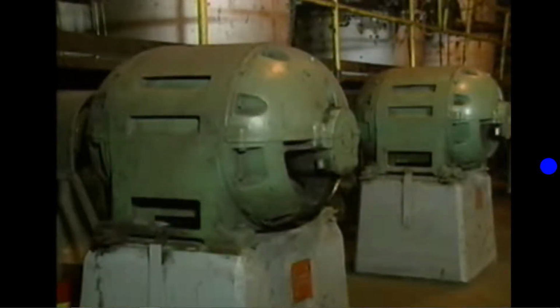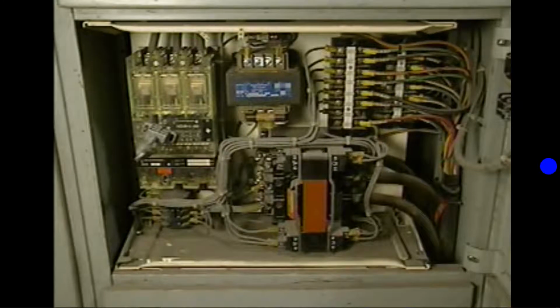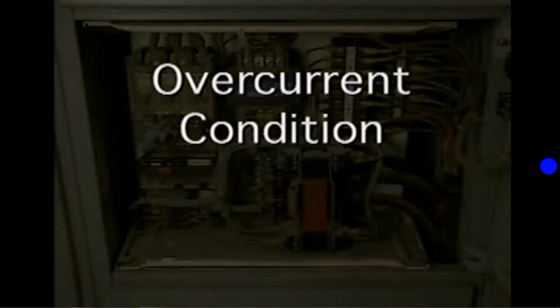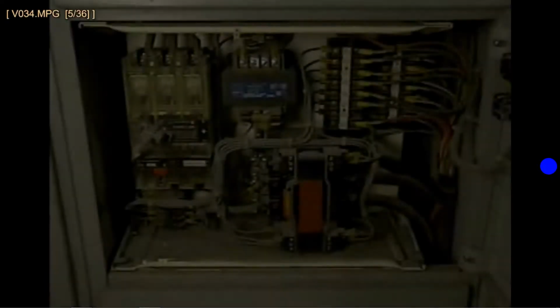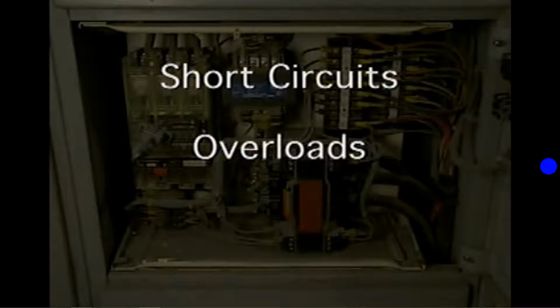Now that we've looked at a typical motor branch, let's focus our attention on the components that protect it. Typically, these components protect a motor branch from high levels of current, which you may hear called an overcurrent condition. Two types of overcurrent conditions that can occur in a motor branch are short circuits and overloads.